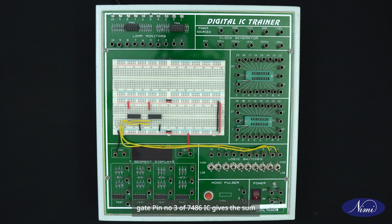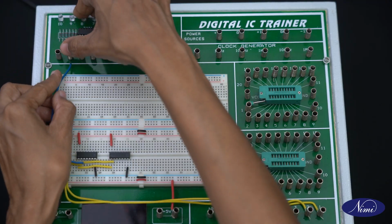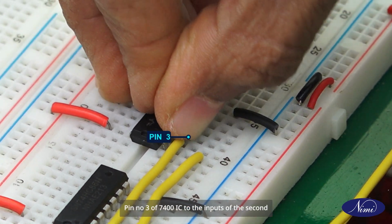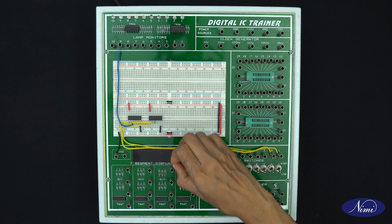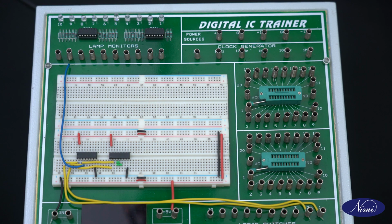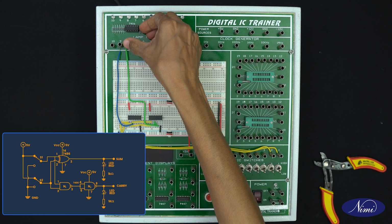The output of the XOR gate, pin number 3 of the 7486 IC, gives the sum. Connect the output pin 3 of the XOR gate to an LED indicator. This will give you the sum. To get the carry, connect the output of the first NAND gate, pin number 3 of the 7400 IC, to the inputs of the second NAND gate, pins 4 and 5 of the 7400 IC. Interconnect pin 3 and pin 5 of IC 7400. The output of the second NAND gate is taken from pin 6 and is connected to the LED indicator. This gives you the carry.